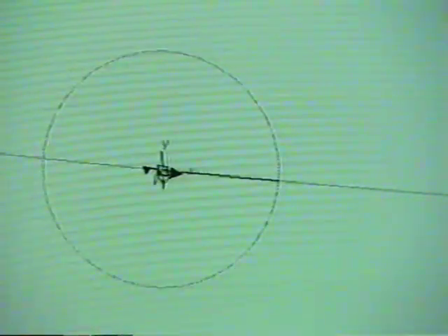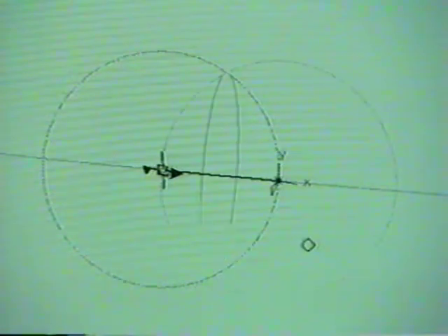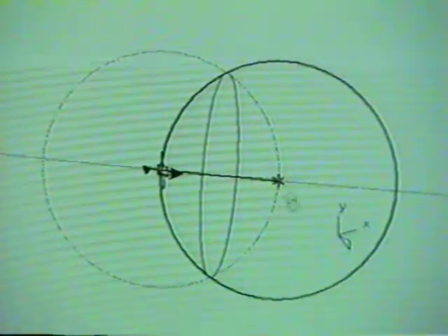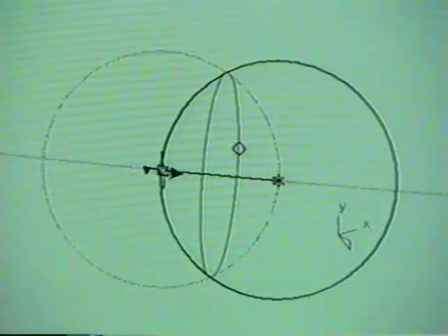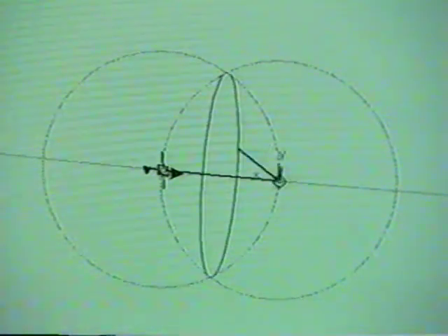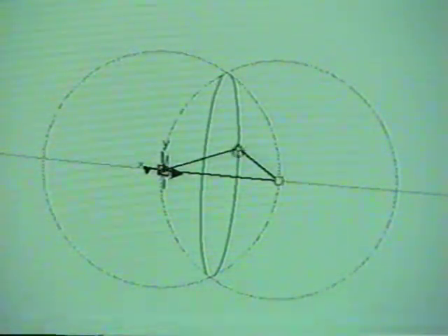When I make the right-hand endpoint hot, it triggers alignment objects just as the anchor did. A new alignment line and sphere appear. The system automatically computes and draws the circle of intersection of the two spheres. I add a line that ends on that intersection circle. Adding one more line, I complete an equilateral triangle in 3 dimensions.